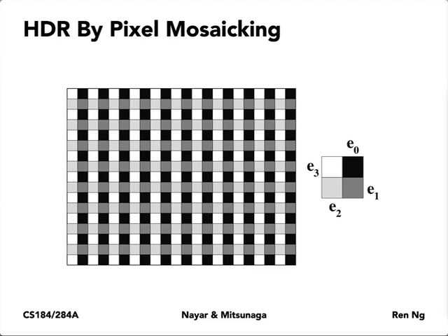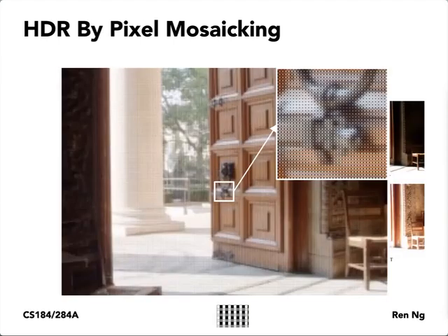And then the goal would be, if you took this one picture, you get this funny raw data set, kind of like the funny color mosaicing data set I showed you earlier, where neighboring pixels would have totally different brightnesses. So you couldn't show it as a photo directly. Rather, you'd have to take this image where each 2x2 set of pixels has one pixel at a very dark to a very bright exposure level, and then figure out how to combine all of them.